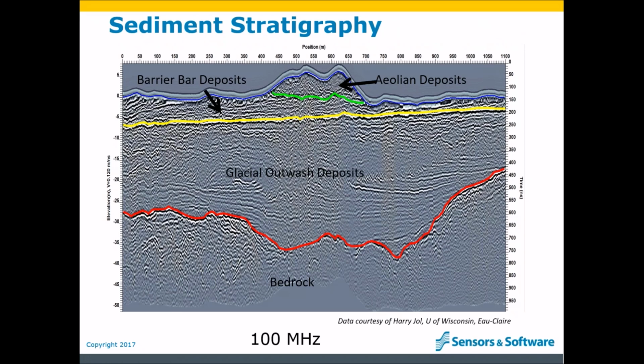To me, the most exciting part of this data is the depth of penetration. Many of you will know that the limiting factor of GPR, and the main factor that prevents GPR from becoming a more common and more widely used technology, is the depth of penetration. 50+ meters of penetration is not typical for GPR. In fact, in most places, 5 meters of penetration is not typical. What today's webinar is about is exploring the quest for deeper GPR data. On the way, I will introduce you to our new Ultra receiver that allows you to see up to twice as deep compared to before.